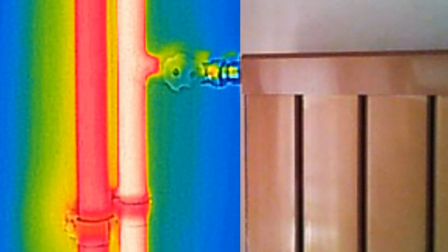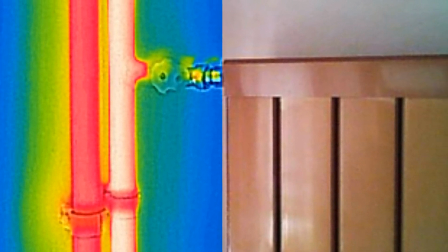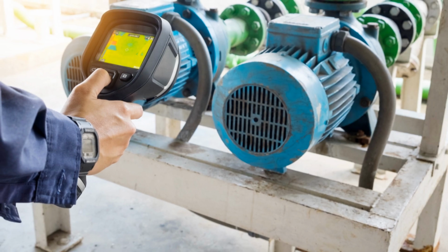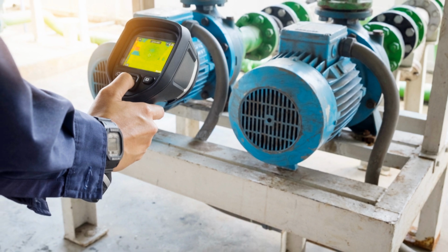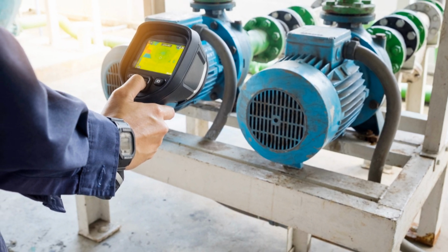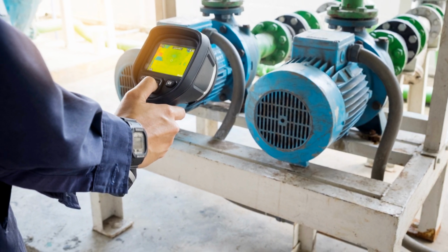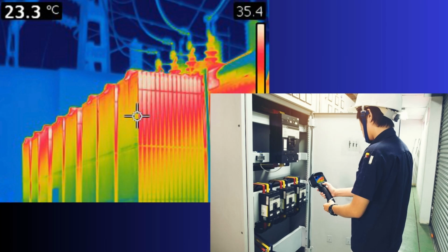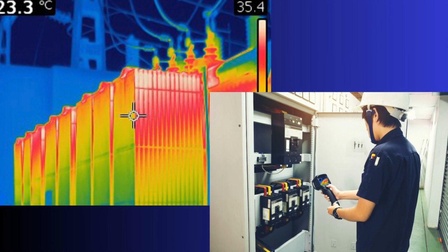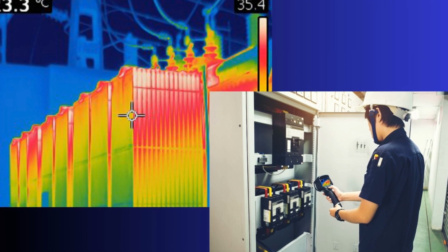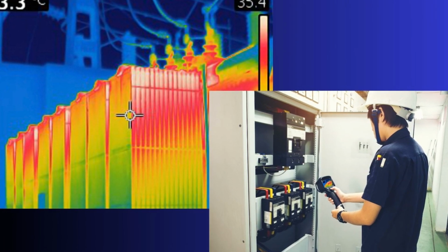Heat map signatures provide a visual representation of failure modes in components under evaluation, revealing critical issues before they escalate. Hotspot clusters, localized overheating in bearings, motors, or mechanical systems, often indicate excessive friction, which can result from misalignment, inadequate lubrication, or early-stage component degradation. If left unaddressed, these heat concentrations may lead to accelerated wear, reduced efficiency, and potential failure.